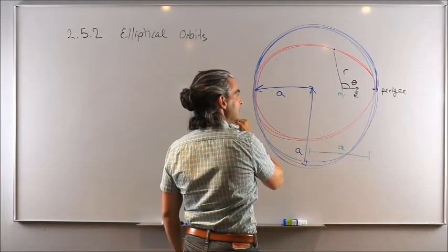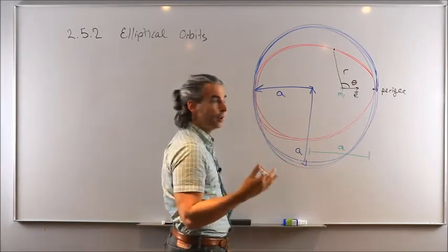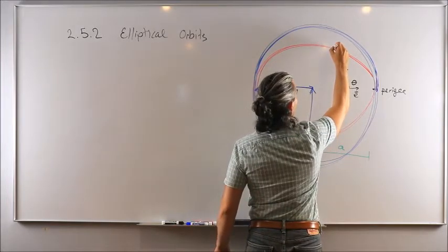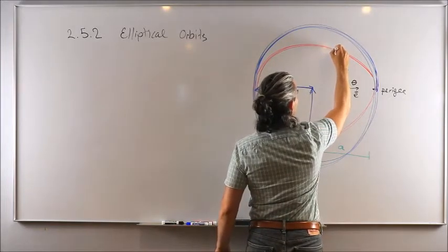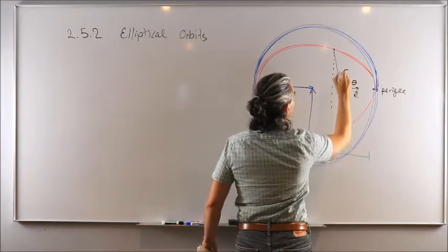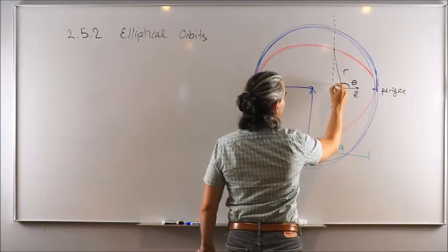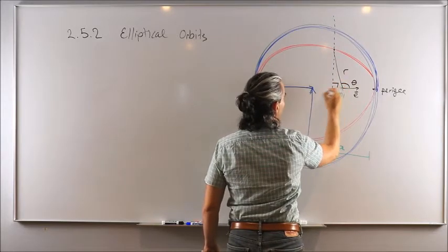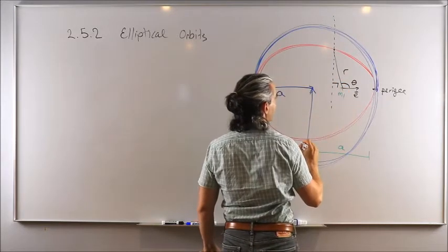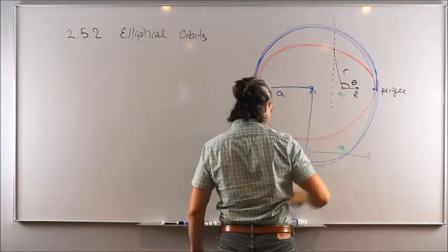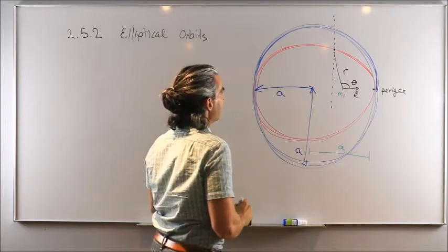So what we're going to do is that to define the eccentric anomaly, we're going to draw a line vertically from the spacecraft position up and down like this, such that it meets the line of semi-major axis here at the 90-degree angle. Okay? Just going to remove the 90-degree angle symbol to not clutter too much the figure.